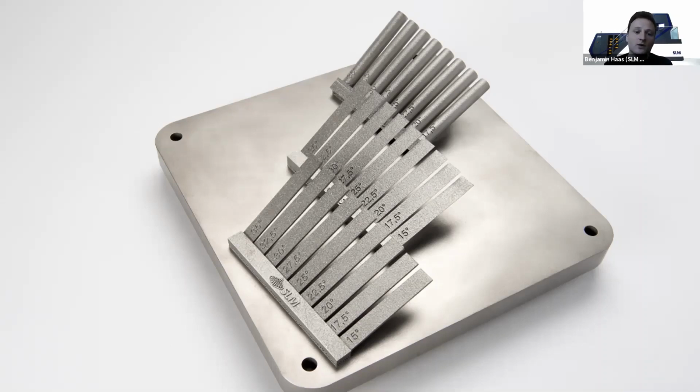And there are a few simple reasons why you want to do that, because first of all, you're melting powder that basically does not have any larger value to it, because in the end you need to remove it, and you're basically generating waste, if you want to say it that dramatically. And of course, it's quite a manual process to remove those supports. There are a few automated processes, to be fair, but those are not really globally distributed. They're not always available, and of course they're not cheap, and there's still an additional post-processing step. And of course, I have to say that supports are there for a reason, because otherwise we would have just left them out in the beginning.